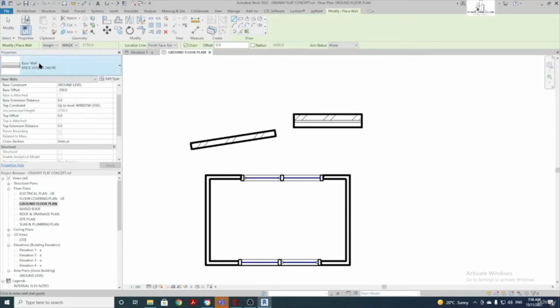So up here we've got a little green bar here. We can modify things like the depth and the height, etc. from this little bar. So depth is basically kind of like where the base of the wall is. So at the moment it says unconnected, but we'll change that to pad level. So that means the base of the wall will be starting at pad level. And then when we change this little drop down menu here to height, at the moment it says unconnected, we'll change that to the pitching height. So it means the top of the wall will finish at the pitching height.